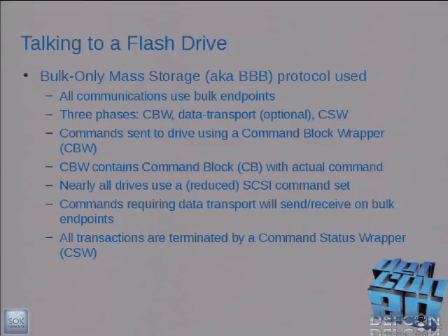All right, so how do you talk to this flash drive anyway? You have this bulk-only mass storage protocol. Sometimes it's called BBB because it's all bulk. And unlike many devices, instead of using the control endpoints, you use the bulk endpoints. And there are 3 phases.